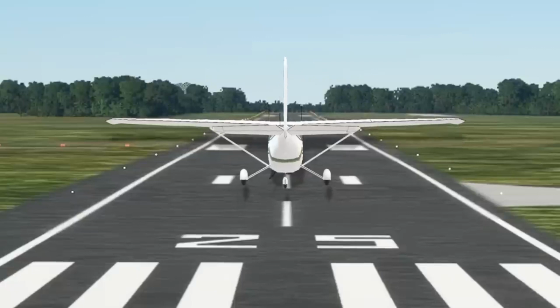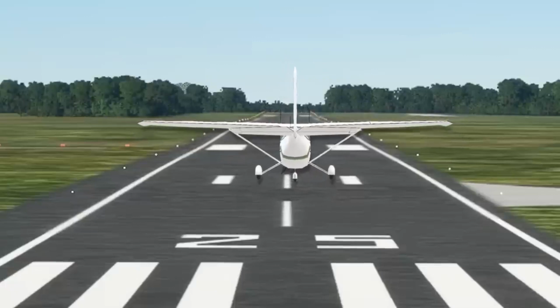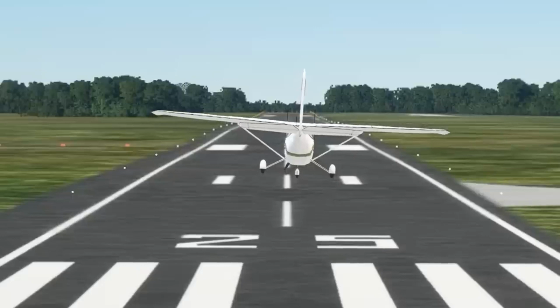Crosswind after landing roll. Particularly during the after landing roll, special attention should be given to maintaining directional control by the use of rudder or nosewheel steering, while keeping the upwind wing from rising by the use of aileron.